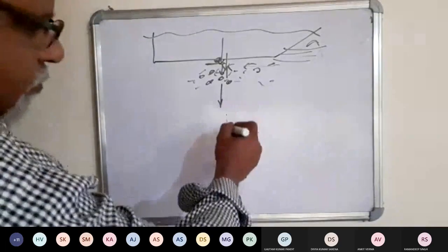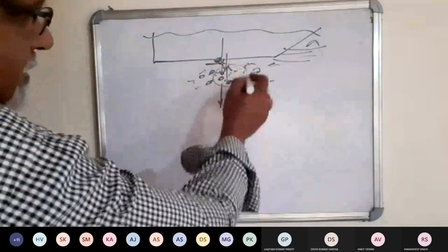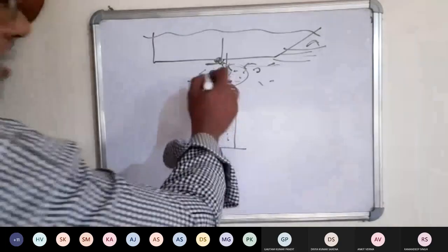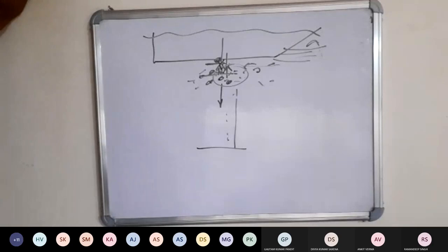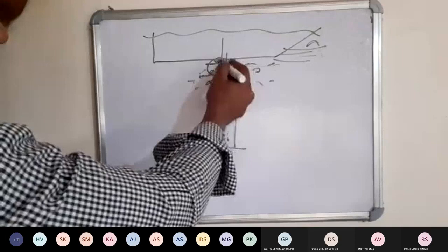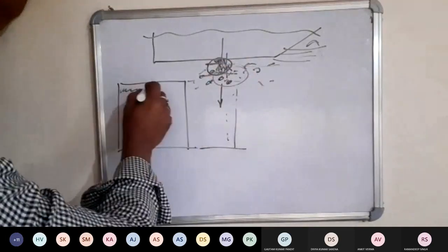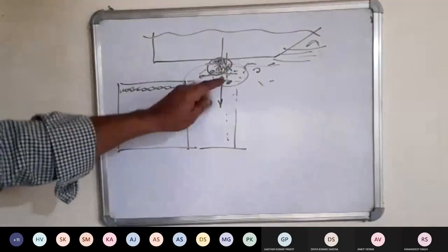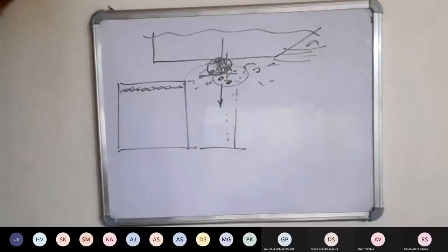If it is going at all, a very weak signal will go, and on the return it has to pass through here again, so there may be a problem. Some bit of energy is also reflected back by these air bubbles. So again, very close to the transducer there is a reflecting surface. So on the recorder, what happens? Again, around the zero line there is recording because some signals are getting reflected back from the layer of bubbles itself.